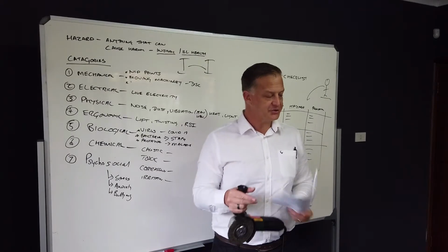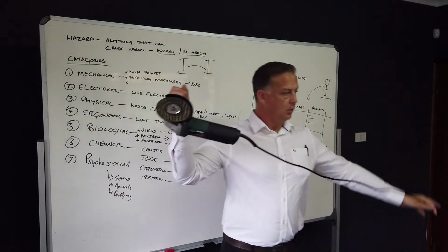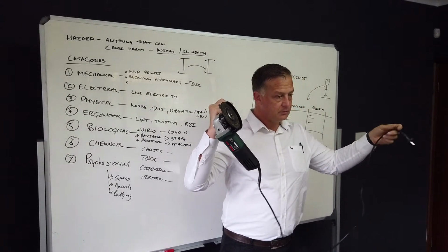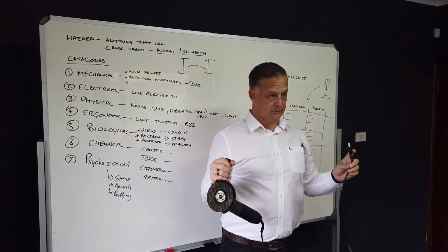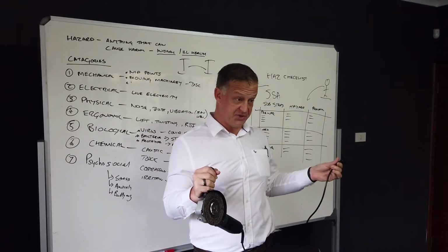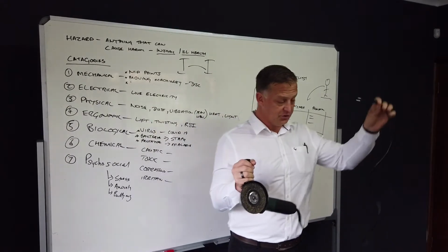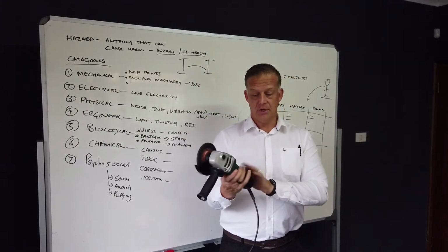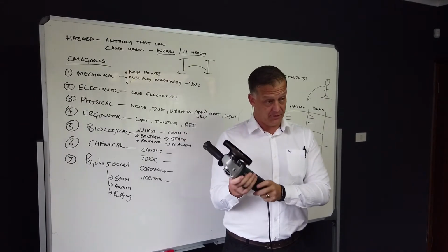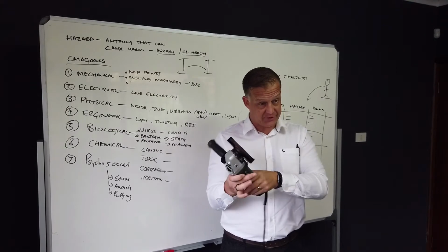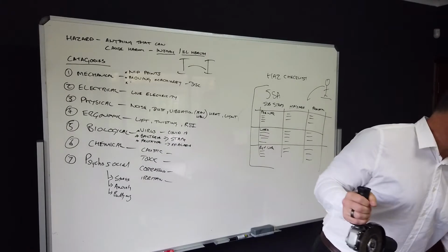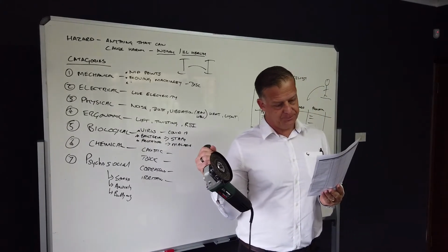Now, let's talk about electrical hazards. So, what do you think is the danger here? It's the cord. It could be the cord when it's uncut or when the wires inside are exposed. Okay, so there's a couple of things. There's the plug that I plug this into, could be a source of electrocution. The cable, and also part of that pre-use inspection is to examine the casing of the piece of equipment, because obviously a lot of the electrical wiring, etc., is on the inside of here. So, yeah, there's the potential for electrocution.